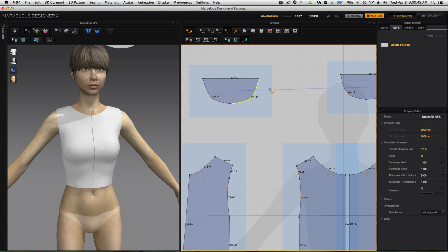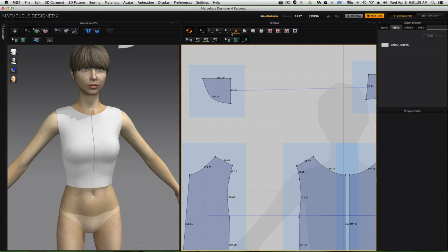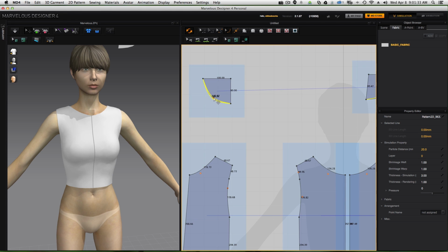This looks pretty good, but the curves are different, and I want this piece to be completely symmetrical. To do this, I'm going to use the Uniform Split on the Add Point tool and split the top line into 2 pieces. Now I switch over to the Edit tool and delete this corner. Now I can use the Curve Point Edit tool to make this look exactly the way I want. When I have it just right, using the Edit tool, I can click on this line to select it, right click, unfold. Now we have a piece that is exactly the same on both sides. And if you don't like the curve, you can simply delete the point again, redraw it, and then unfold.